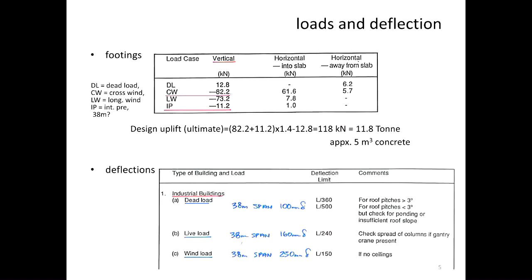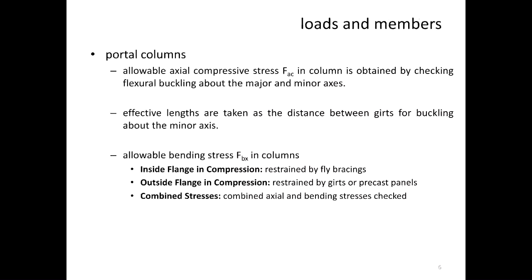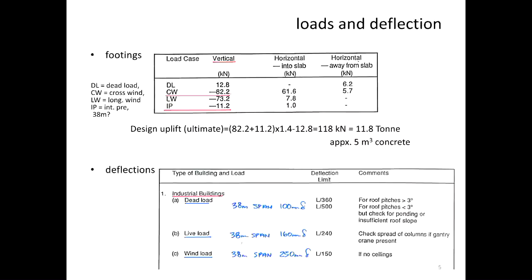Because that's an important aspect you need to understand, why we calculate ultimate load. Generally, when you have an industrial structure, when you go to buildings, for example, you will see that the lower part of it is precast concrete, and above is lightweight. That is being done basically because of that uplift load. That uplift load is what actually ties down the structure. So that's one aspect of that precast panel.